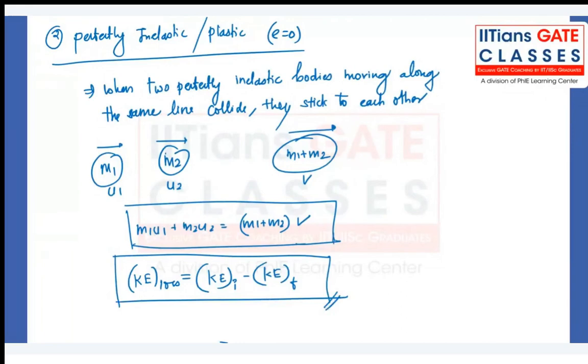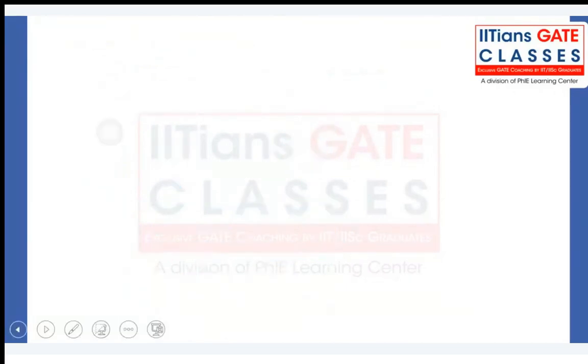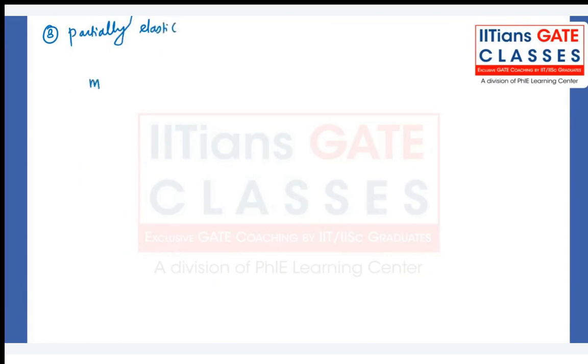And the last one, that is partially elastic. Let me explain how it will look. The last one is the third one, partially elastic. Okay. So basically two bodies, M1 moving with velocity U1, another body M2 moving with velocity U2. After the impact, they will deform a little bit and they'll regain their original shape a little bit. So it's a combination of deformation. In the previous case the complete deformation is there, they will not regain their shape. So here a little bit of deformation.